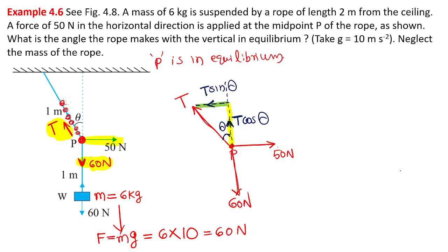So the next is, all the inclined forces to be resolved or split into horizontal and vertical components. So the resultant is 0, means that net horizontal force is 0. I can say like this. The vector notation is not required. We can solve the problem like this. Net horizontal force 0. Why net horizontal force 0? The point P does not move horizontally, that is the reason.